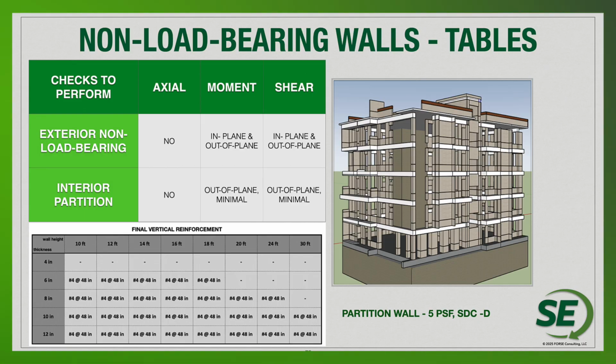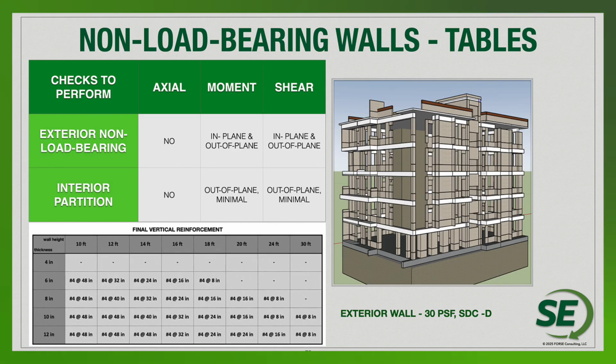We know that we have more and more reinforcement demands, which again is really going to govern the overall design. But again, if we can get into an exterior wall, we have more and more forces that we can consider for the exterior walls if we could add load-bearing designs. Here you can see the non-load-bearing designs actually get a lot more reinforcement requirements because we're not moving up on that curve. We're still staying with pretty much a pure bending design situation.